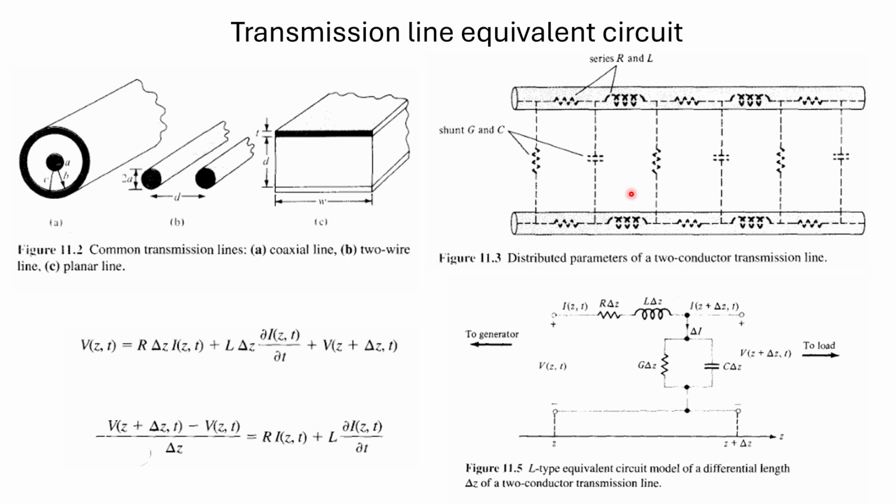Now, similarly, you can redraw these equivalent circuits to find the values of the voltage and the current on any transmission line. So here we have resistance, inductance, and then conductance and capacitance. Suppose the entire length is z. So let's consider z plus del z.